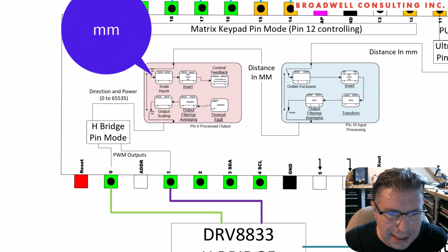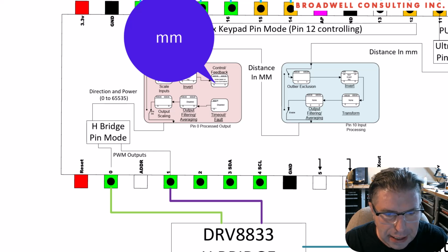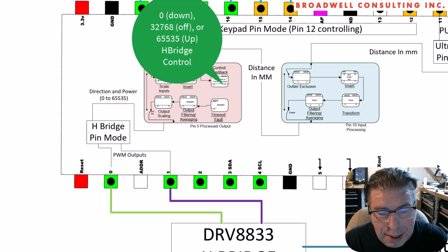So it pulled that data and brought it in. We didn't end up scaling it. We used it in its inherent millimeters. We didn't have to invert it. Our control feedback was hysteresis, although we ended up controlling it dynamically from the Arduino, changing the control algorithm as needed to move it up or down based on our needs.